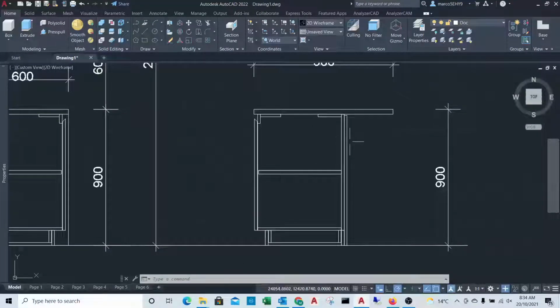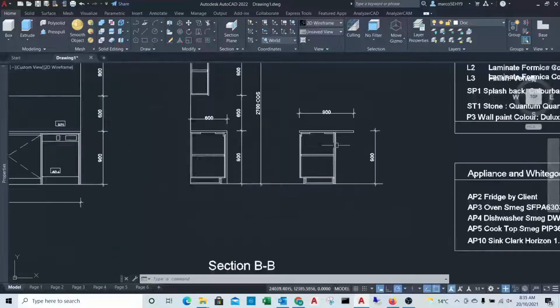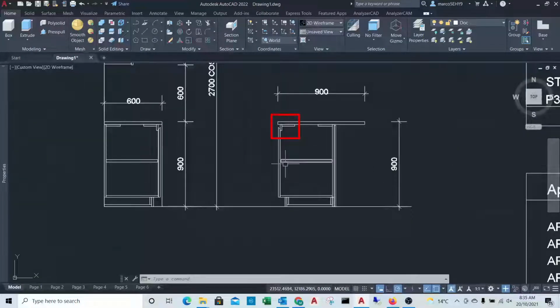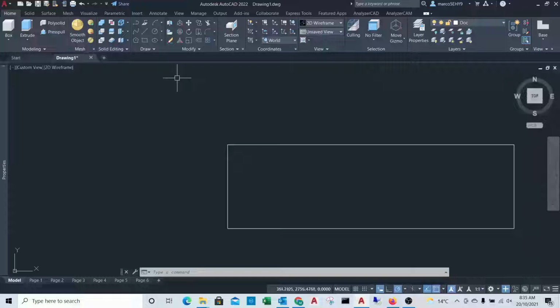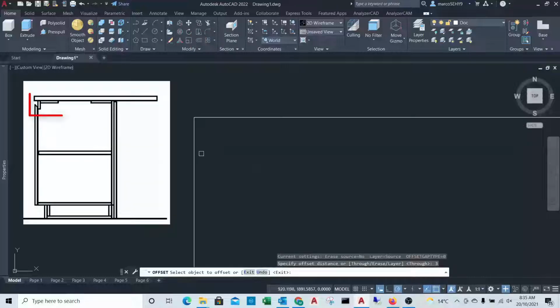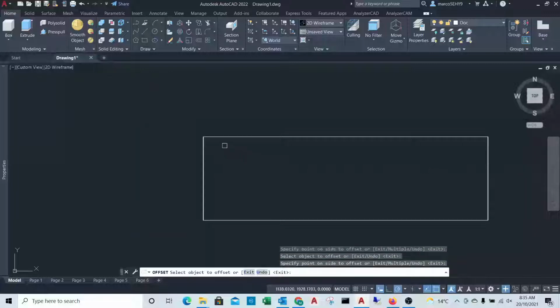The architectural drawing asks for cabinets that are 600 millimeters in depth. You also need to check if the benchtop has a pencil round on the front edge. It would not work to have the cabinets completely flush with the benchtop front and side edges. We need to allow for building hardware and visual tolerances. To allow for this, we need to set the cabinets a couple of millimeters from the edges. Here you can see a finger pull handle on the cabinet door. You have to make allowance for this in your setback.